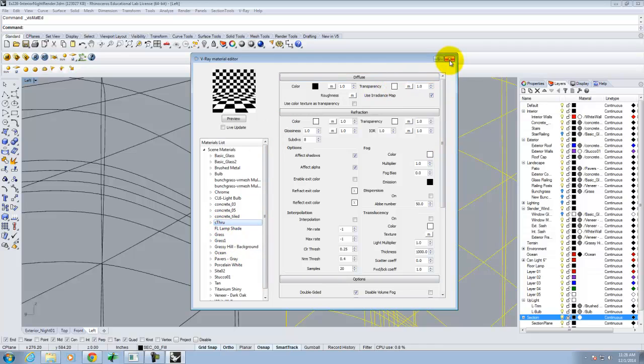Oh, you know what? I failed miserably on one thing that I probably should have told you all first. Before you do the split, make sure you save as your work, because if you don't, it's a permanent change to your work. So I probably just screwed up my file, but so be it. Don't follow my lead. Make sure you save as before you do the split, because as soon as you do the split is when you mess everything up. So always do a save as. It is written out in the step-by-steps everywhere. I think it's bolded in the little handout that I gave you. So I try to hit you over the head.